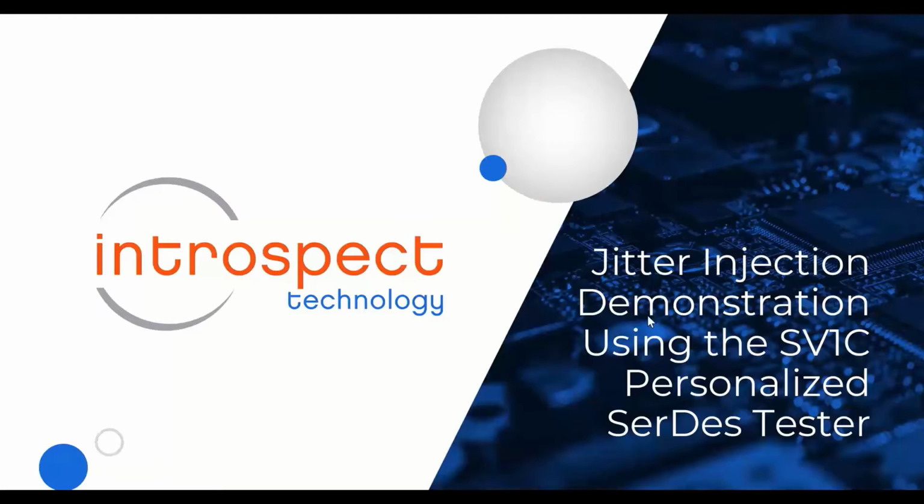Today, we'll be demonstrating how to inject sinusoidal jitter onto an output waveform generated by the SV1C Personalized SerDes Tester. Jitter injection is a feature available in several of our Introspect products, and it's very easy to program this using the Introspect ESP software interface.